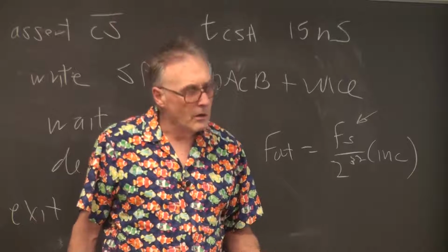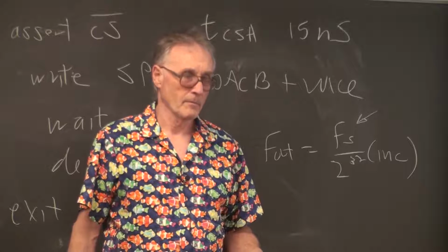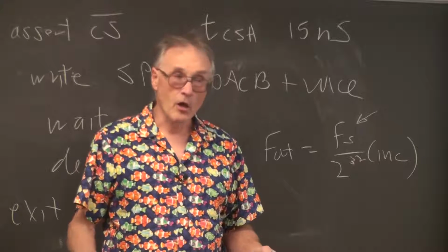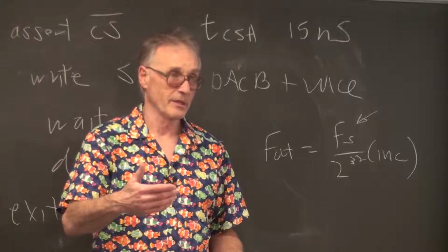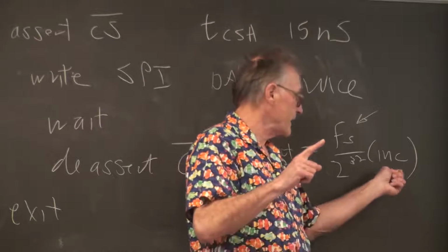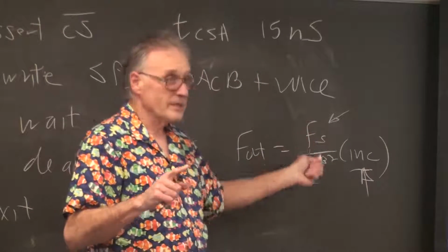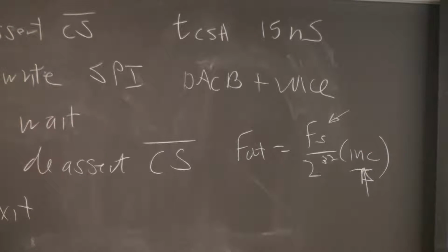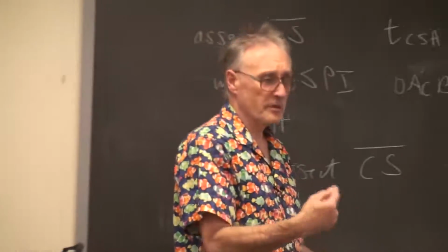I was using timer cycle time in all of that. Fs is always set by a timer in my code because I'm always doing an interrupt service routine based. The increment is set in the code, but Fs in everything I've written is set as the execution rate of an interrupt service routine.